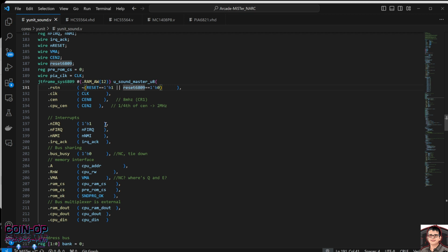There is a startup where the bong noise plays, and then after the POST, when you get to the high score screen of Smash TV, you'll hear another set of bongs, and that is the talkback interface resetting the 6809. When you reset the 6809, that's when the bong sound plays every time. That's like its own POST, or way of posting.